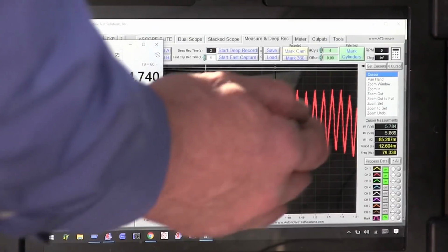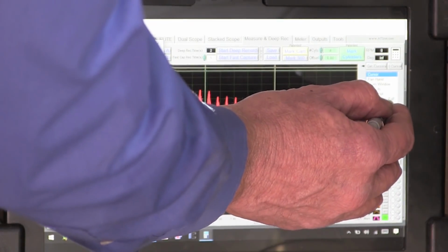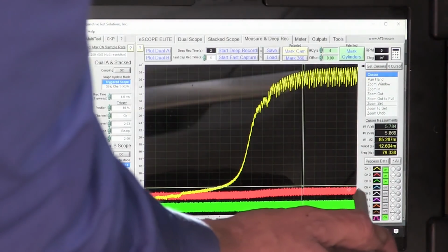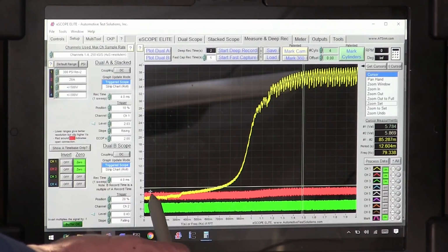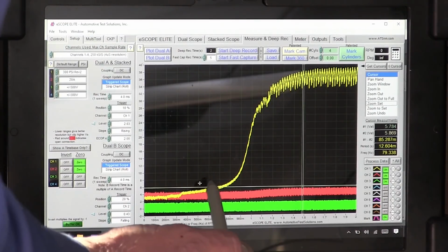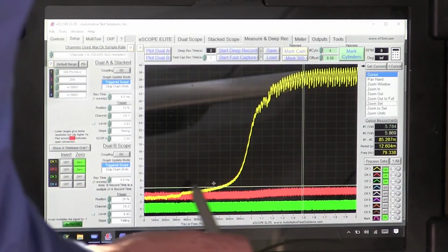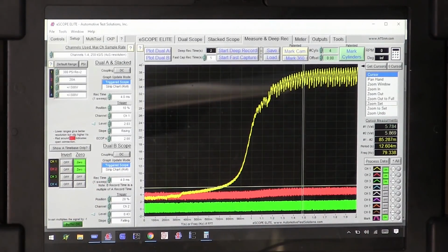You can see that really easily here. Let me go back out and show you what I'm talking about. Do you see how the current stayed level all the way across? Even though we don't have pressure here, and then we got pressure, the current draw to the pump didn't change. That's because the pressure at the motor, where we're checking the pressures, is on the other side of the restriction. The pump just sees solid pressure against it. So this is a really good test so you don't waste time.